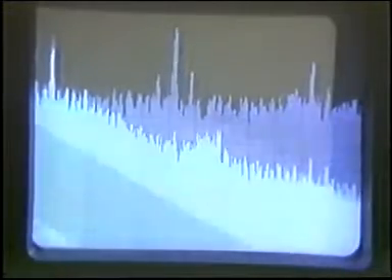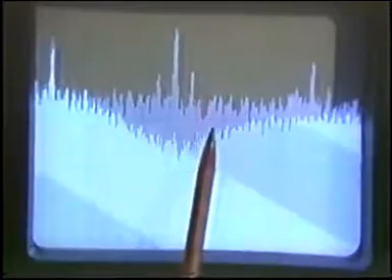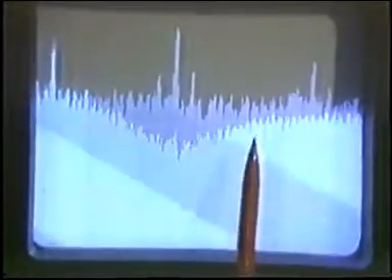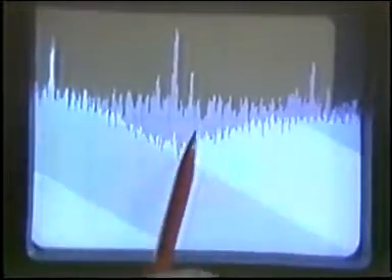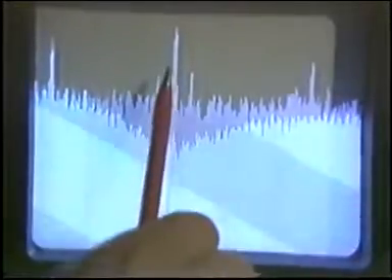And now we're beginning to see the effect of the notch. There's a notch in the response, just there, and then we level out again. In other words, this filter isn't attenuating the high frequency noise very much, but it is putting a notch in there, which is attenuating the interfering signal. And as far as we can tell from the spectrum, it's gone completely.